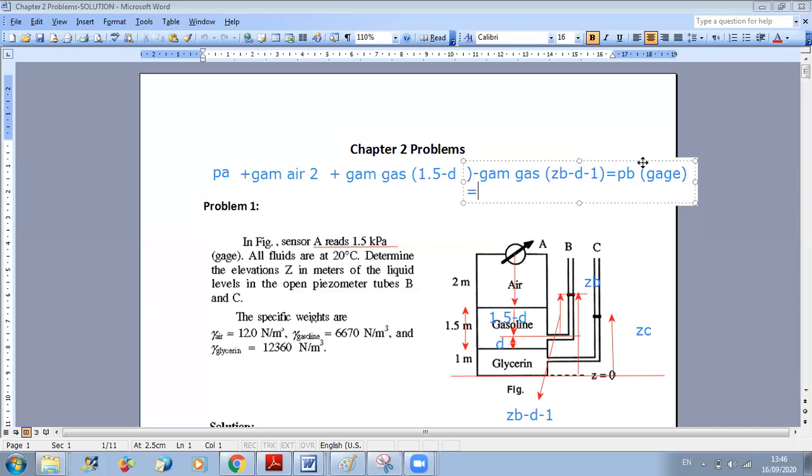Okay? Because what is gauge pressure, you remember? Gauge pressure is P absolute minus P atmospheric. Yes. So I am putting my zero reference at atmospheric level. So if in a place I have atmospheric pressure, this is absolute pressure, PA. And if I want to express it in gauge pressure, I subtract the atmospheric pressure. So when I am exposed to the atmosphere, my gauge pressure is equal to 0.